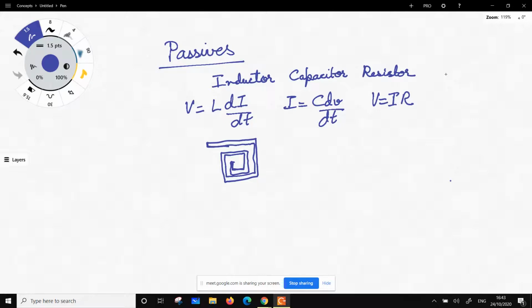Let's say this is M0, and I can choose a different metal to come out. So this may be M1. If you are on M1, which is a higher metal than the coil, then M0 is the lower metal, so you can come out as an underpass; otherwise it is an overpass.